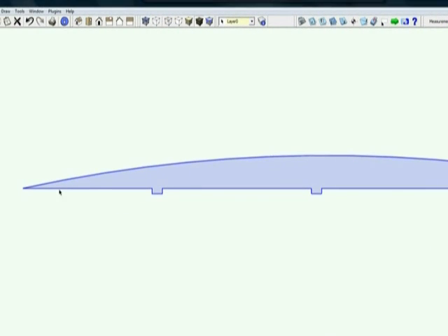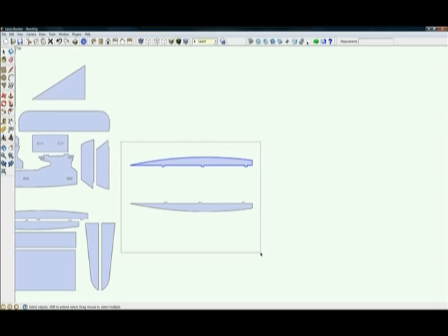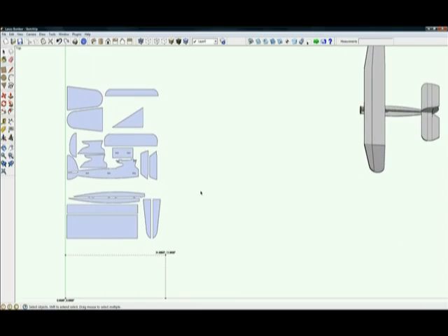and so forth. Using the Weld tool, anytime you have arcs like that, to unify all the line segments as one will mean that when you make the machine code to go to your CNC machine, it will cut that piece out in one continuous motion. So that's something that I thought was worth bringing up, because if you don't get in the habit of doing that and you're making your files for CNC machines, you can take a file that might cut out in 5 minutes and then make it take 2.5 hours. And I know this from experience. So I wanted to share that information with you. That is a very useful plugin.